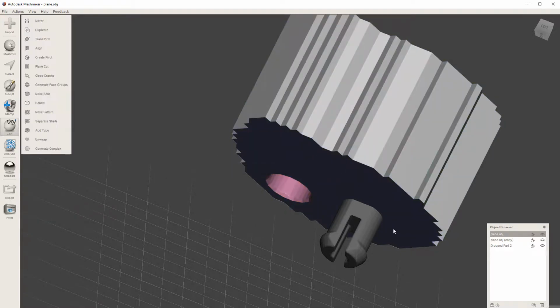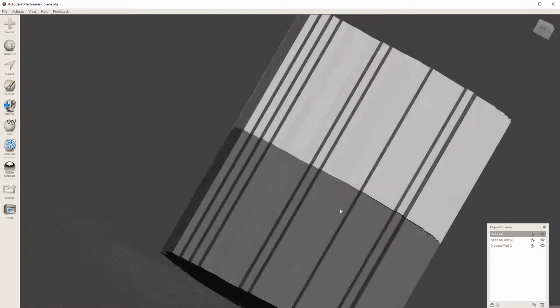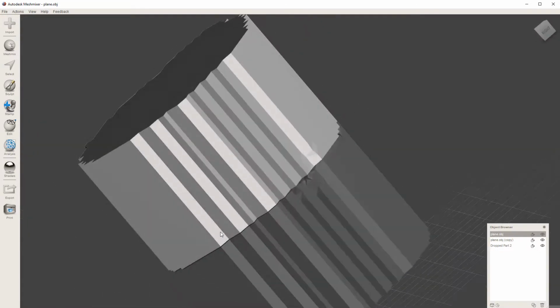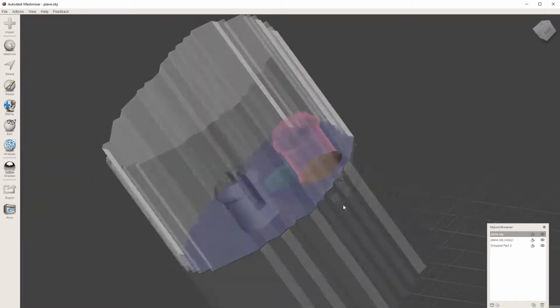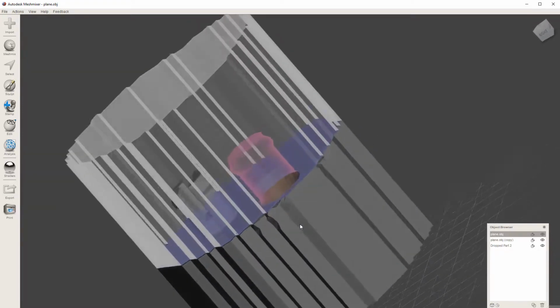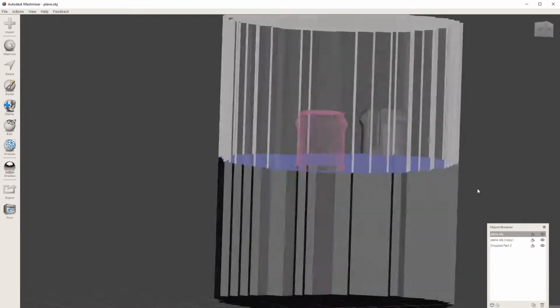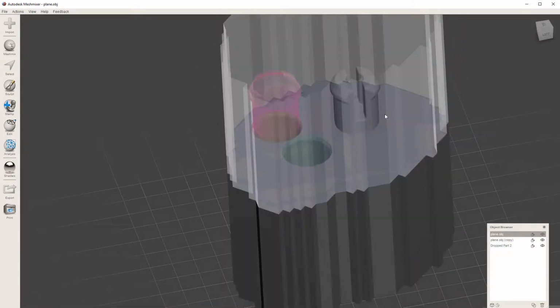And now when a pin goes in here, let me turn on a different shader to show you. It would show that it would go right inside of there, and that would be a kind of perfect match. If you put in two pins like this, and again, you would need to test for tolerances, it would effectively pretty much lock. It wouldn't be the strongest lock in the world, but it would be pretty strong if you were connecting these two things together.